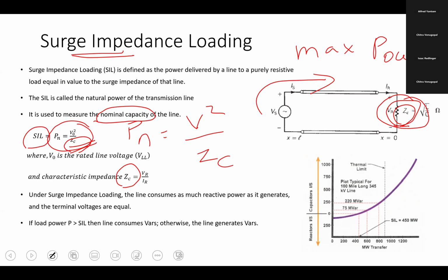Suppose anything happens, you are preparing the source to match the load. So balance. That is because I told you already, the lines are not storage devices. They cannot store any power. You can ask me, oh, inductance is storing current, so what happens to the power? Pure inductance cannot store power.